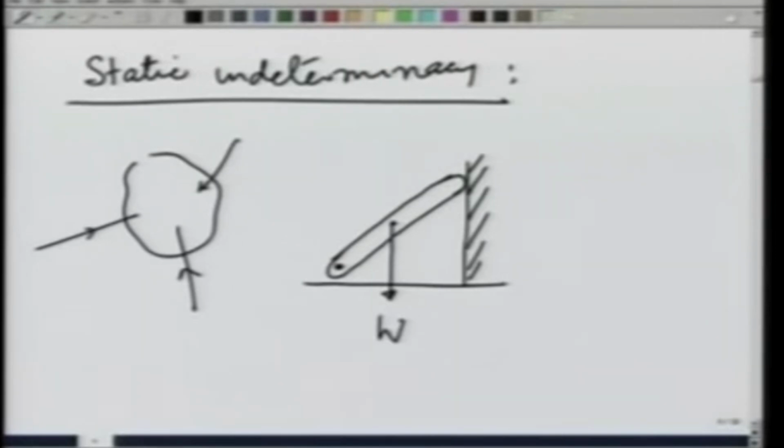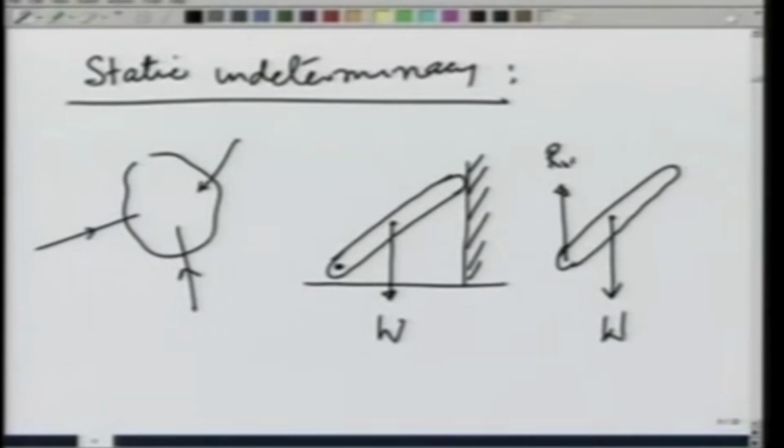If I look at the free body diagram of the rod, it will have a force acting down, which is its weight, a reaction in the y direction due to the pin, one in the x direction due to the pin, and a normal reaction from the wall. These forces are sufficient to bring this rod into equilibrium.